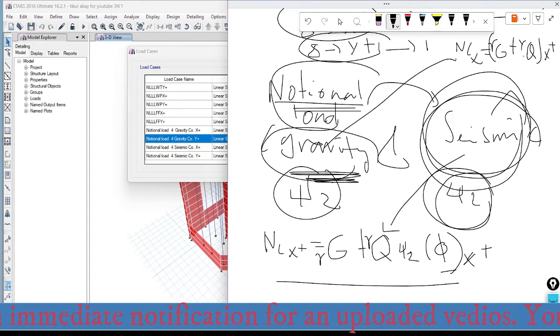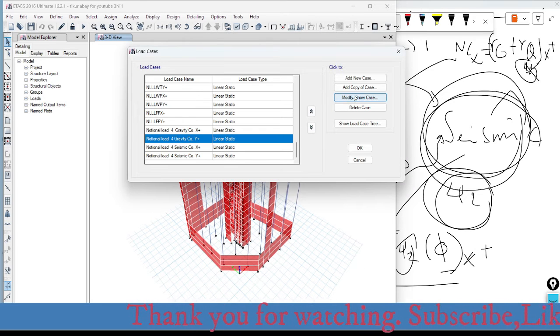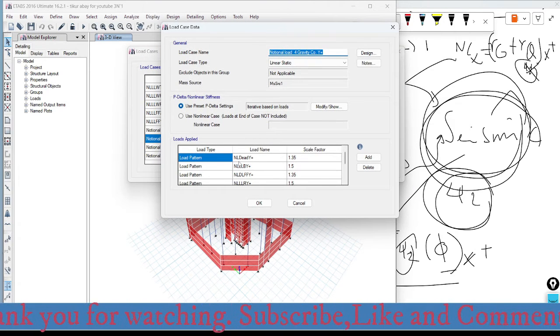Here in this case, there is no need to use the live load reduction factor phi 2. But for the seismic case we need to use the live load reduction factor because we are defining the imperfection load with reference to the seismic condition. That is why it is just modified.